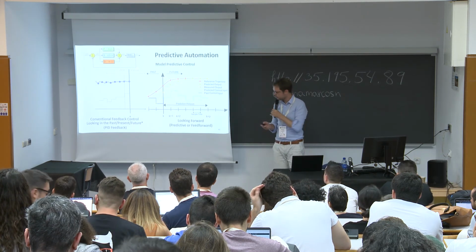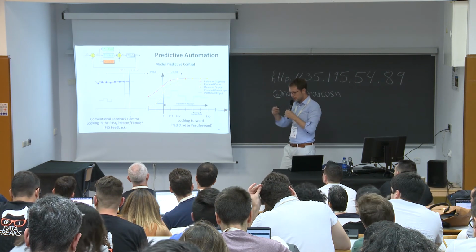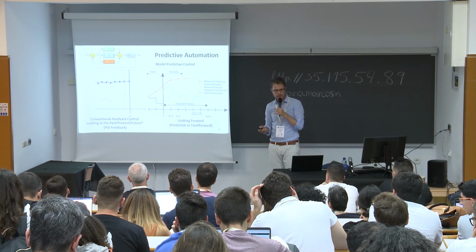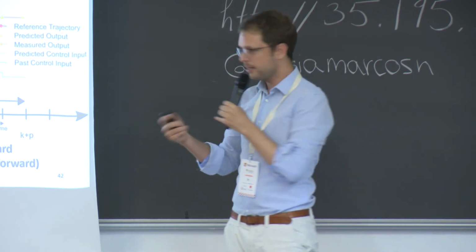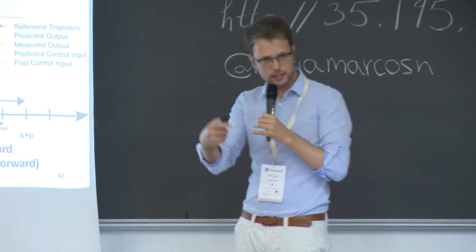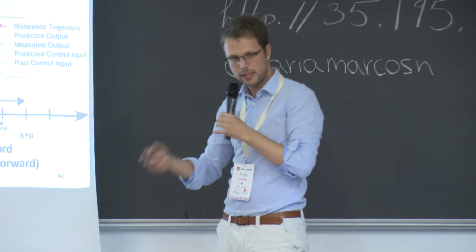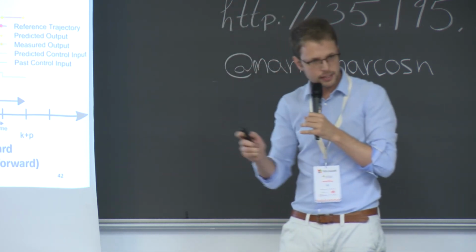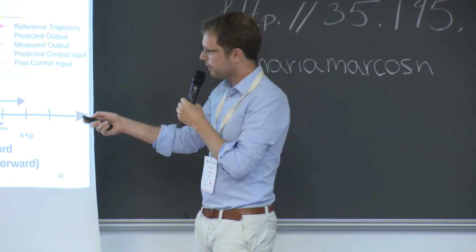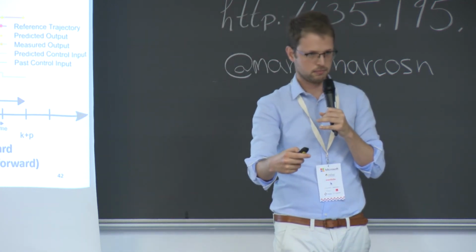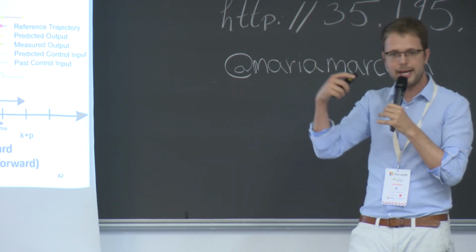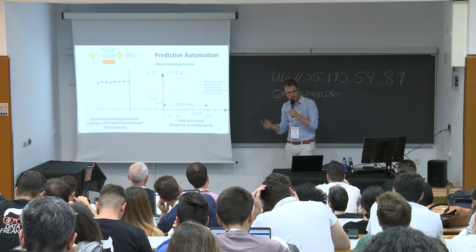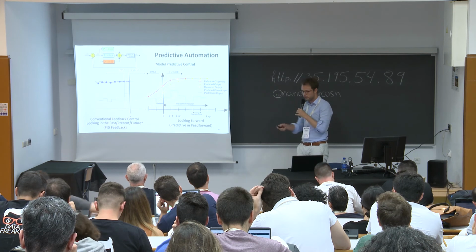And all of this brings us to predictive automation, because we have dynamical systems. We have PID controllers, which basically look at the error you have and then give you the output. So it's a direct correlation between the current error, the past error, and the immediate future. But there is model predictive control, which has similarities to reinforcement learning, which you can do with Gecko. It will look into the future with several steps, and it's way more powerful because you can look ahead. What series of actions can I take to optimize this? And the model doesn't need to be perfect because every instant you will repeat this operation.